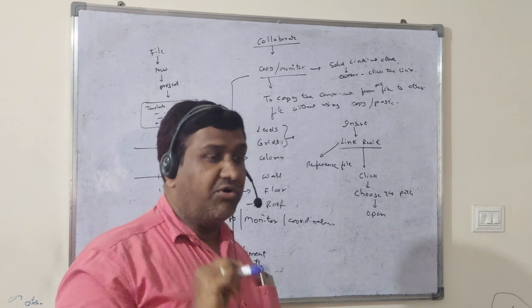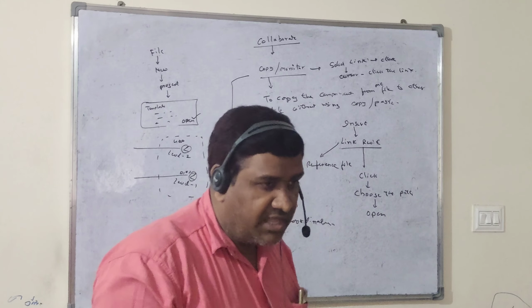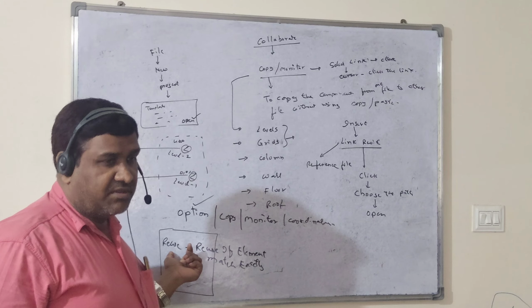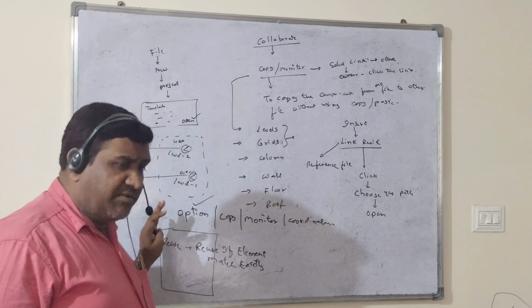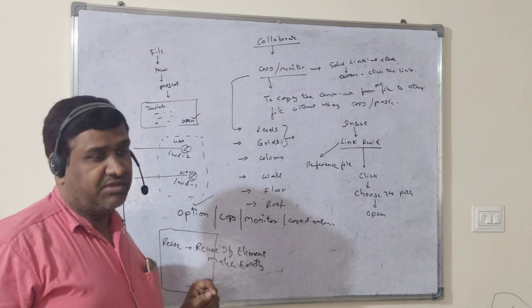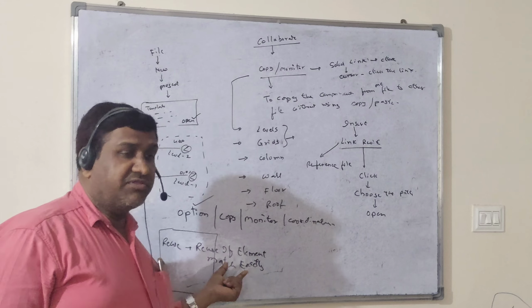Because the first menu you have to go to is the option. If you click the option, one palette will appear in front of you. In the palette, there is one menu, reuse. Beside it there will also be 2-3 menus, but you just follow this reuse menu. So you just click the reuse menu, where there is a drop menu.